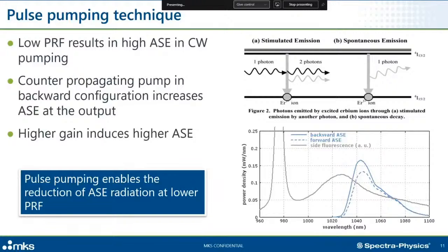And you want to shift that repetition rate very fast from very high to very low, and you need your energy to be fixed. So one of the things you could do is just control the current, and as the repetition rate goes down, you lower the current. Unfortunately, it's very difficult to change very high currents like 10 amps very fast, and also if you keep the current fixed and you go to very low repetition rates, usually the problem is ASE.